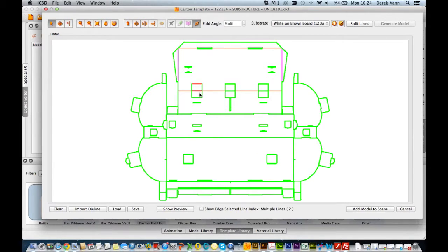The small fold lines can then be selected together, again using the Shift key, clicking and dragging so that these can be changed to individual folds using the Folds button. The next set of double-lined folds cannot be selected together, but by holding the Shift key again, the top lines can be selected as they are collinear and they can be made into linked folds. This can then be repeated by Shift key selecting the bottom lines and also making them into linked folds. The remaining folds are changed to individual folds.